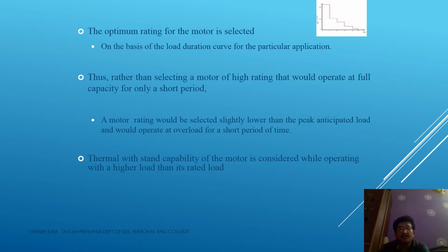The motor rating would be selected slightly lower than the peak anticipated load, and it would operate at overload for a short period of time.